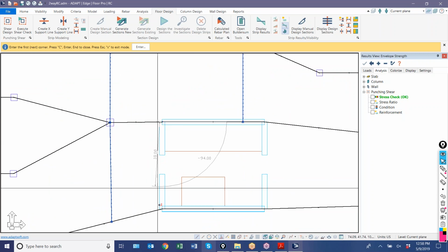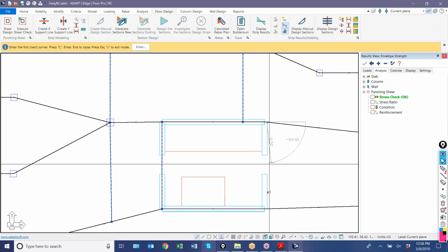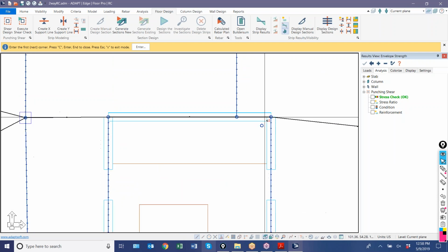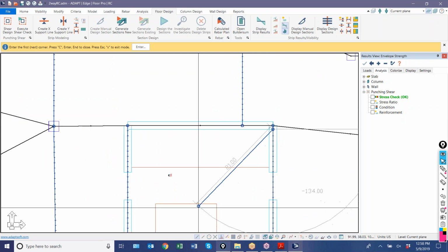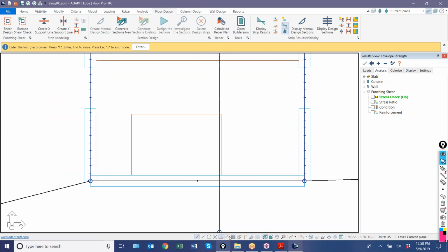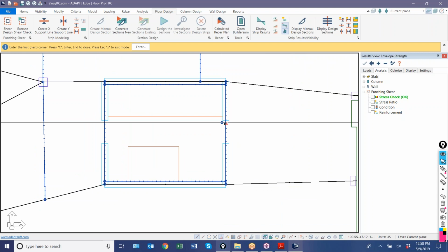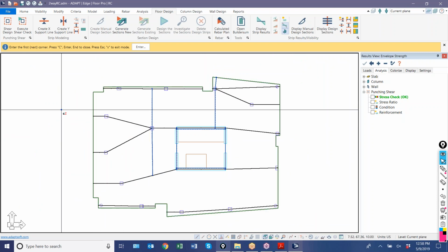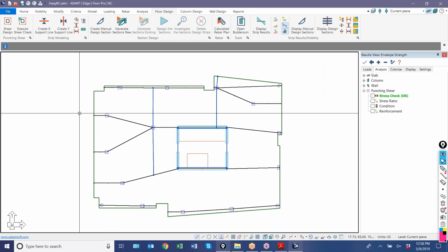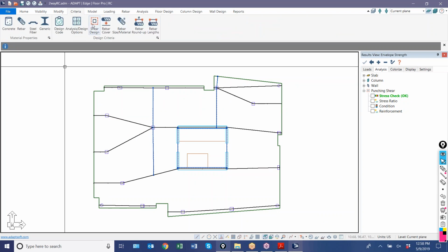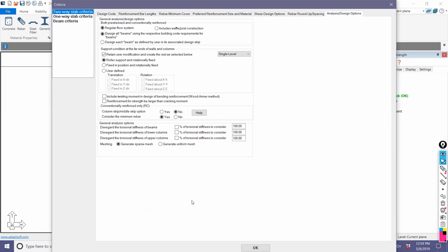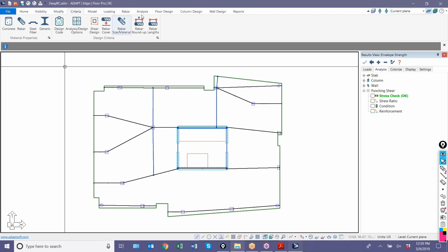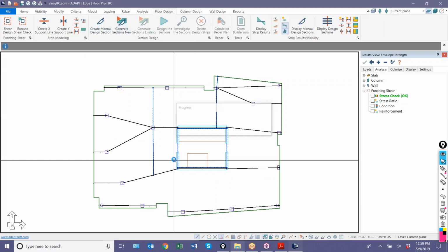And I also want to bound out this core. So I'll just put a splitter there, one there, and I'll go from side to side now. So I'll do one like so, and like this. So I completely isolate this using splitters from the rest of the slab. Now if I generate my strips without the use of middle strips, I'll go back and generate the sections.